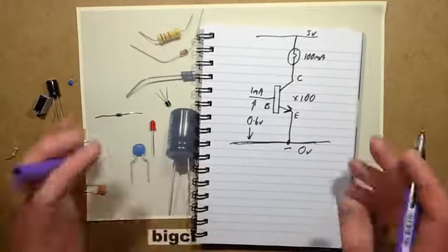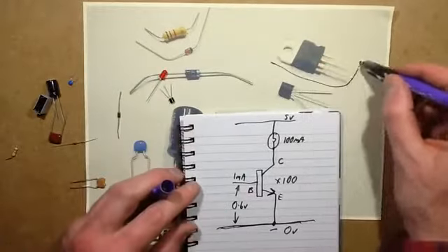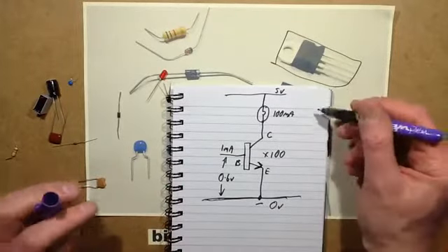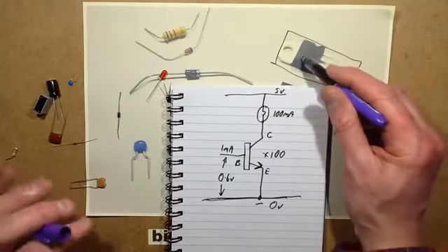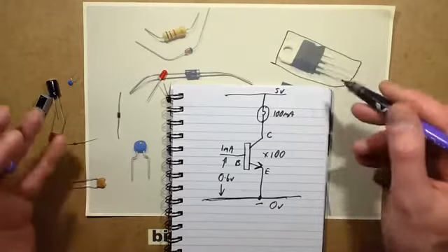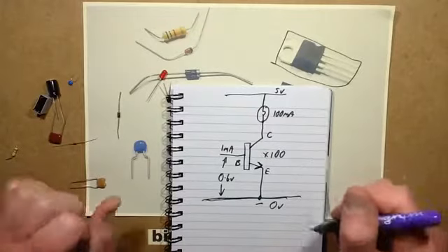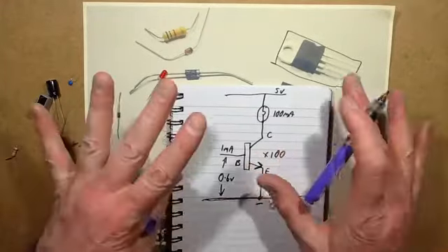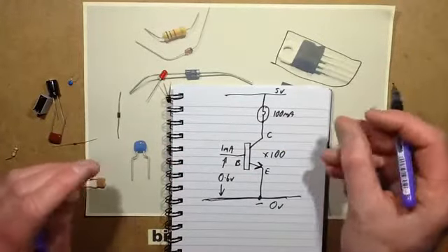Other types of transistors are things like this one pictured here, a MOSFET, and they're optimized for switching really high loads. I chose the STP36NF06L for my RGB controllers because one of the nicest things about it is that it can handle a lot of current, and its on-state resistance is so low that it doesn't impede the flow of current when it's turned on, to such a level that it doesn't really get very warm.